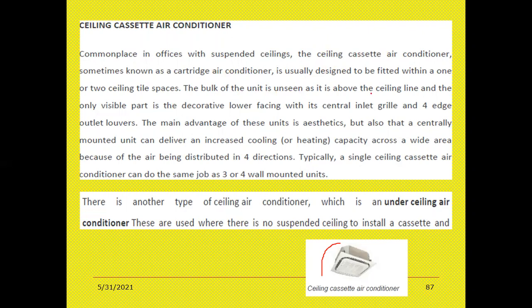On the tube side, freon fluid passes at extremely low temperature, while on the shell side the brine solution is passed. Right, after passing through the evaporator, the brine solution gets chilled and is pumped to various air handling units. So we have two sides: one is the brine solution, the other side is where freon fluid passes, right?